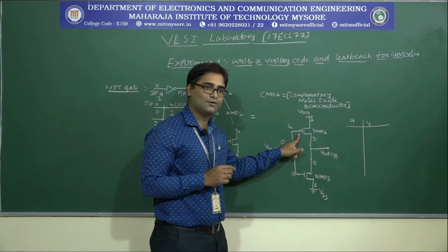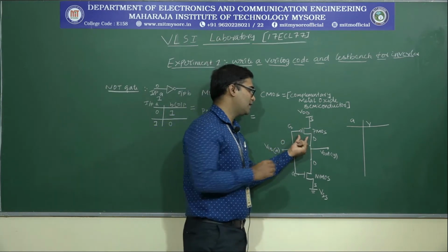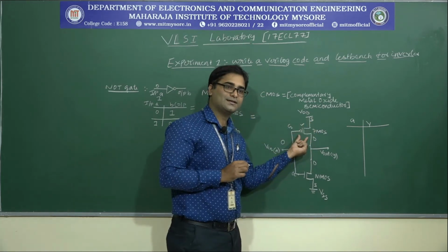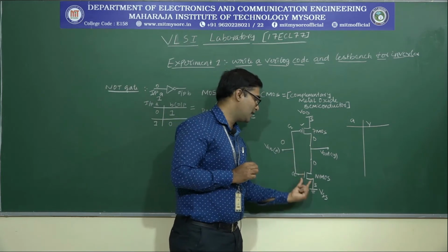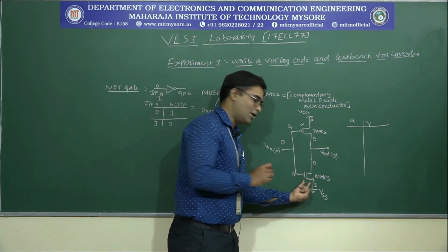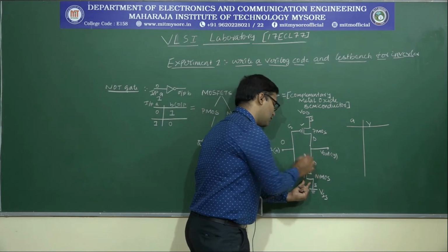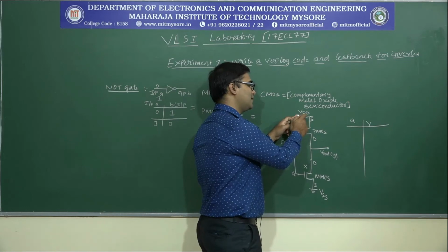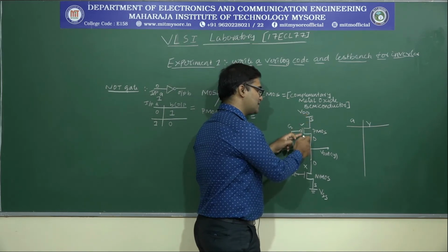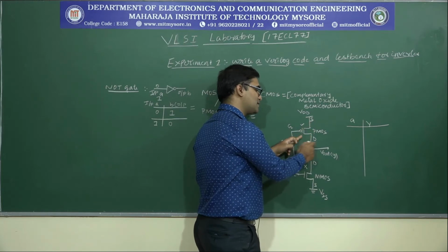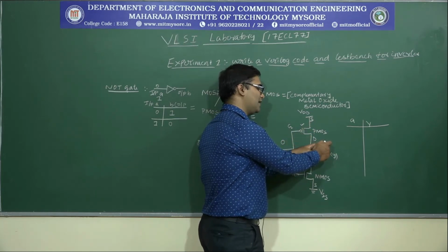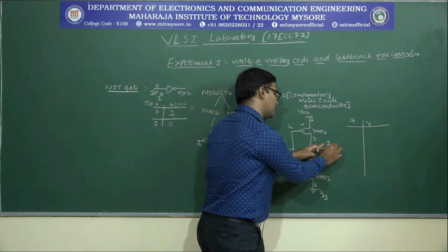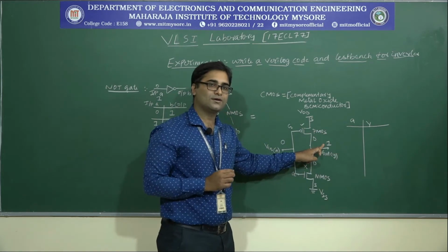That means this PMOS transistor is on and it is a closed switch now, and the NMOS transistor is off and it is an open switch, and whatever value is present at VDD moves through the PMOS transistor and is obtained at the output, which we define as a digital logic 1.